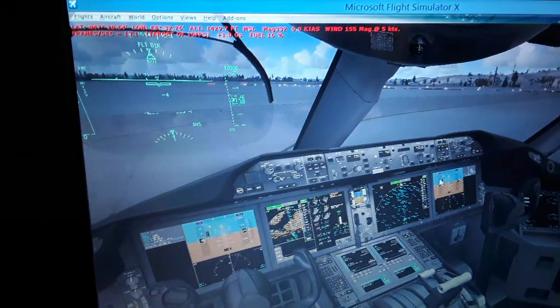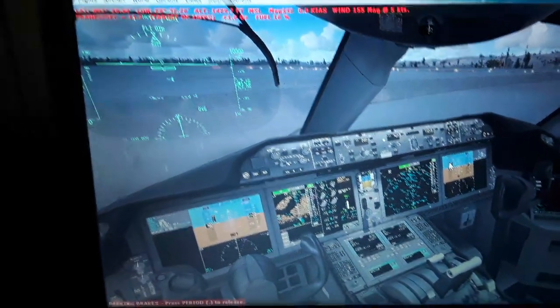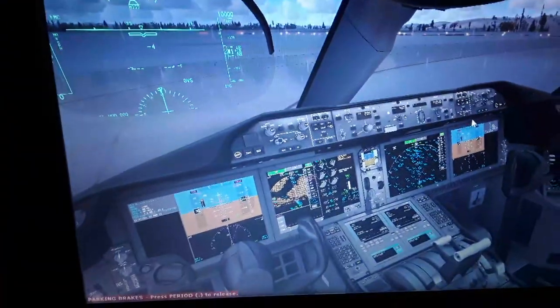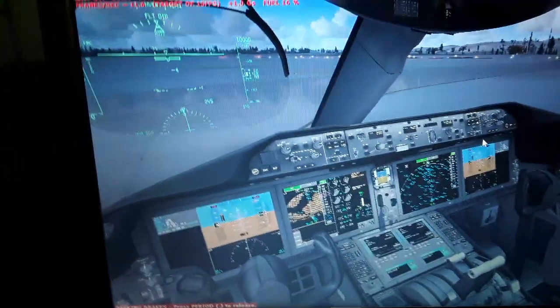So we have also the navigation display. The navigation display shows the horizontal and vertical profile of the aircraft as it flies. You can see the terrain and weather reflections from the weather radar. You can see the terrain displayed with red, amber and green indication, and also the lakes, the rivers and the sea in blue. You can see the horizontal and vertical profile of the terrain around you. Also the distance is displayed.